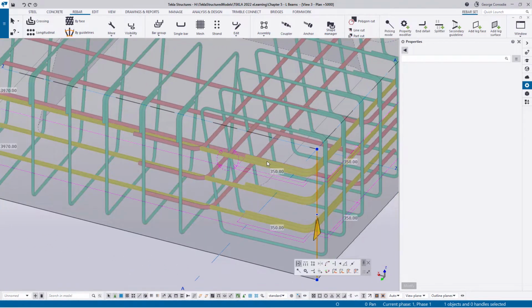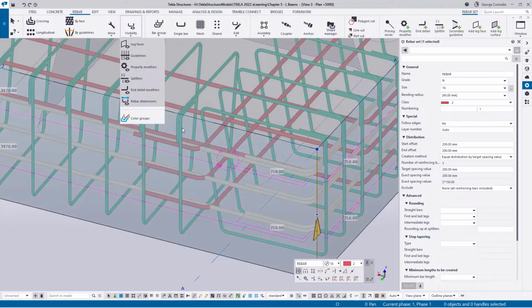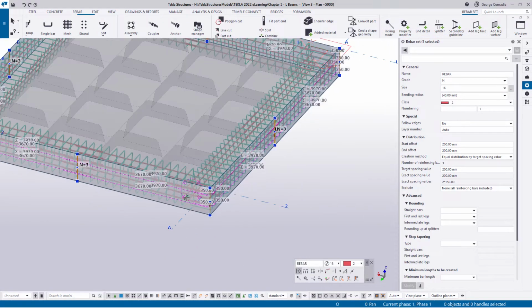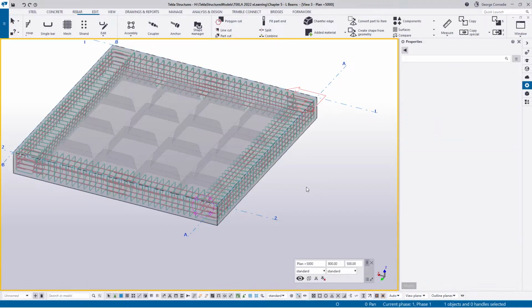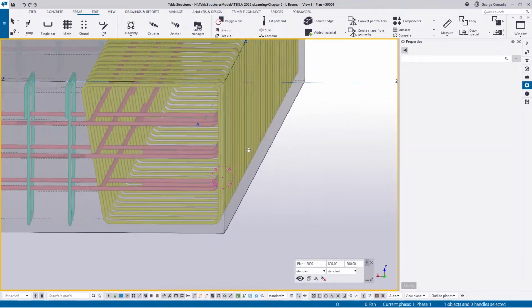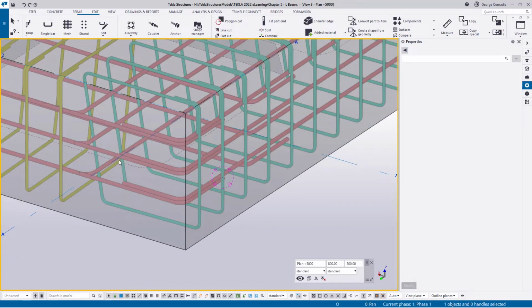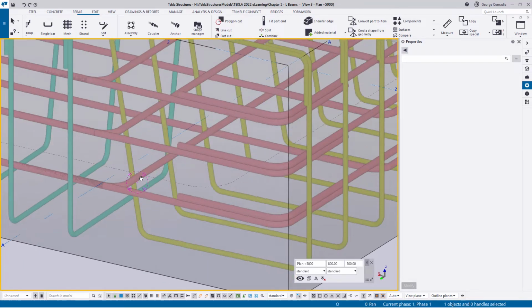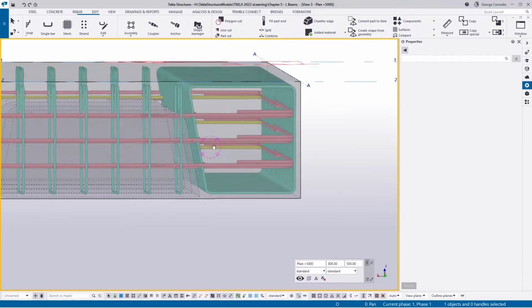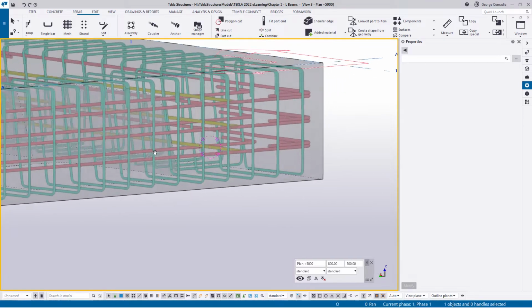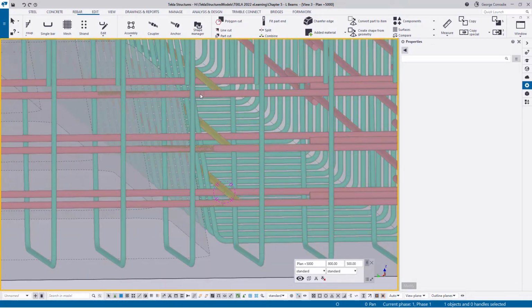So if we click on this bar now and we put on our leg faces and look at the faces, we can see all three sides are on 3, 3, 3, 3. So if we take that and say we need you to move up outside one layer, 1. So that changes to 2. And now if we look at that, they're pretty much on par with those. So all we need to do to fix this issue is to look at what's going to be the easiest to move, the outside or the inside bars, because you can see the inside bars here are now lapping with those.